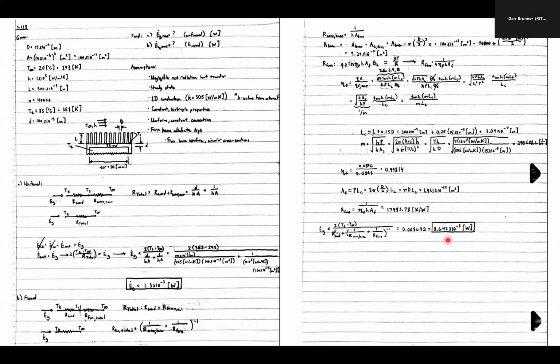And so what that tells you is that the thermal resistance due to the fins is likely not contributing too much to the total rate of heat transfer. And so a lot of it is coming from the convection occurring either at the surface of the unfinned chip or on the fins themselves, if you do include fins.